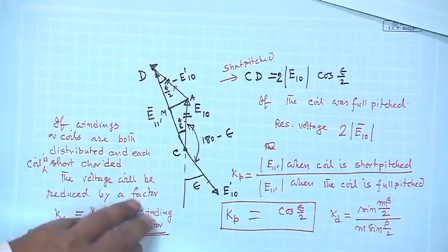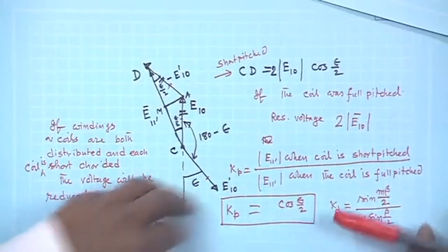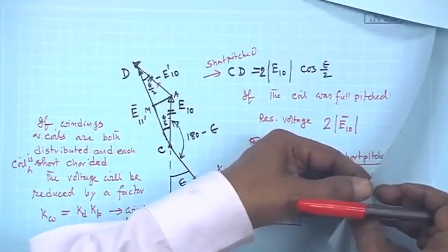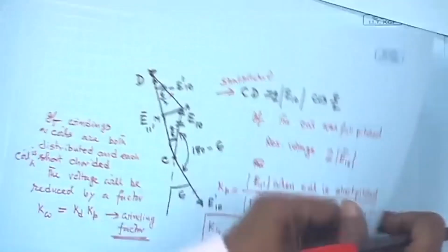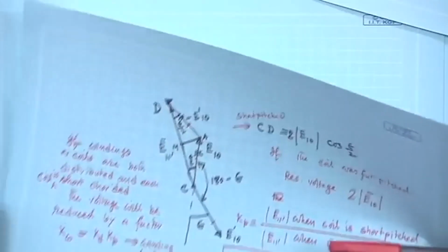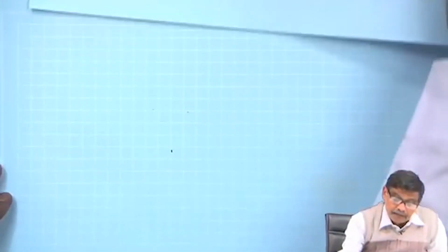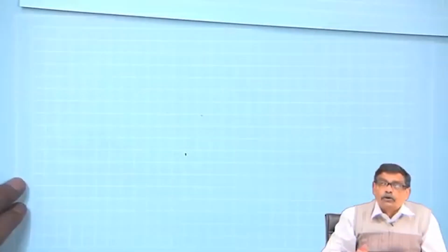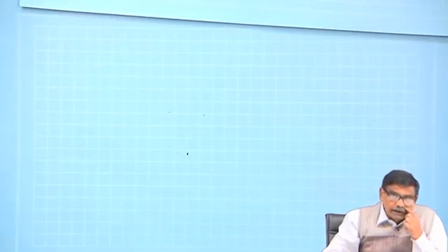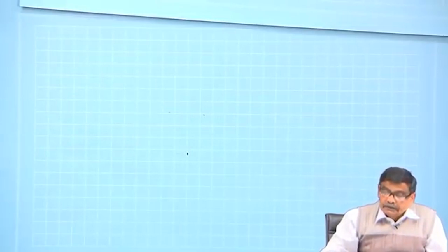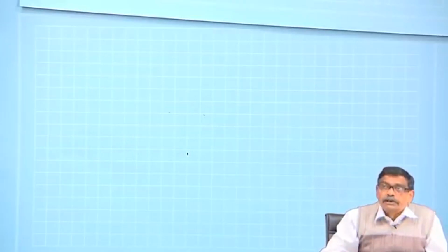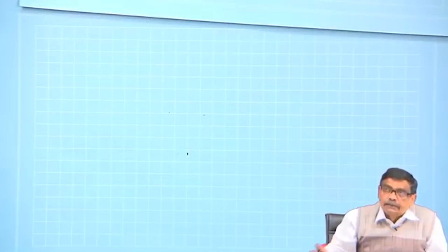You recall that the B distribution in space is not purely sinusoidal. It will have space harmonics, and these harmonics are odd. Fundamental is first, the next predominant harmonic is third, and then fifth, seventh, and so on. Of course, their amplitudes are progressively decreasing.